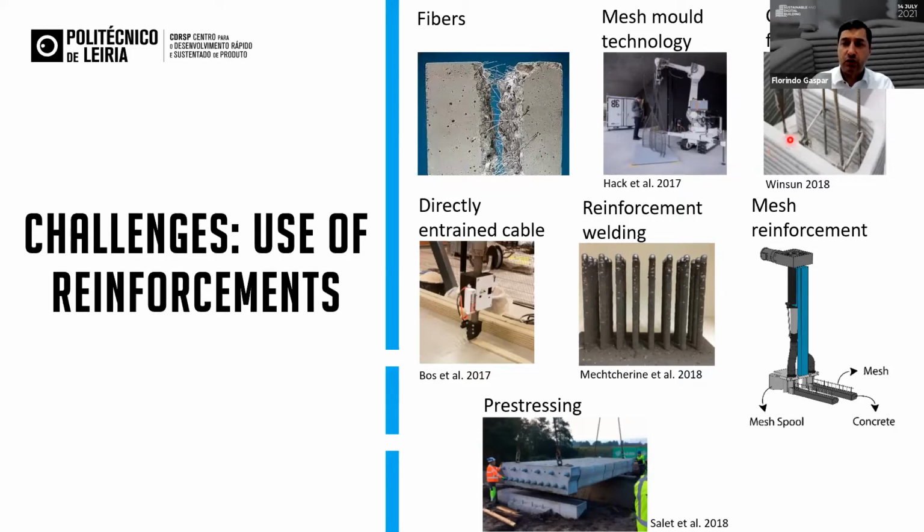Another example is the use of formworks, like you can see here in the figure. We can reinforce concrete using the 3D printed concrete as a formwork. It's not about using the printed concrete itself as a structural element. In this case, it works only as the formwork. We in this case are not using 3D printing for the structural part. However, it could be an advantage to get a formwork with a certain shape that we have difficulty in doing by the traditional process.